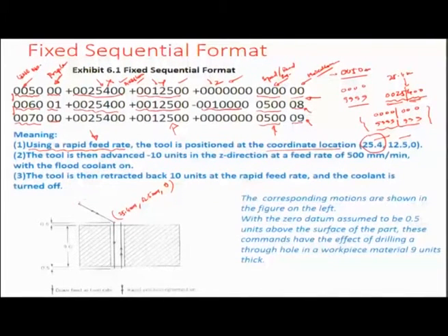So let's say the tool was positioned somewhere here corresponding to some other address, so it would definitely read the overall XYZ motion and come to this particular position at a rapid rate. One must remember that when the tool is not being engaged into the workpiece, you could use a very rapid feed kind of a strategy, but if it is engaged, then obviously the rate of material removal will define its speed of feed, and so you can't just rapidly position as you may have the luxury to do at the very beginning when the tool has still not started its interaction with the workpiece.